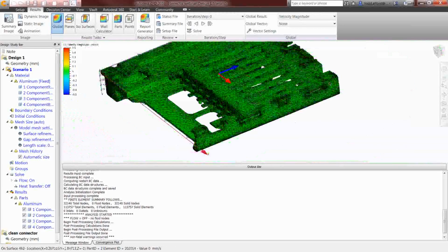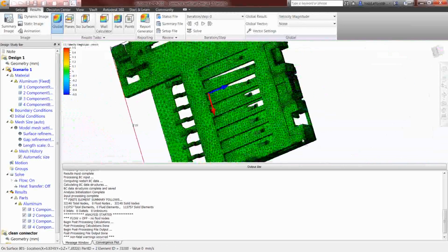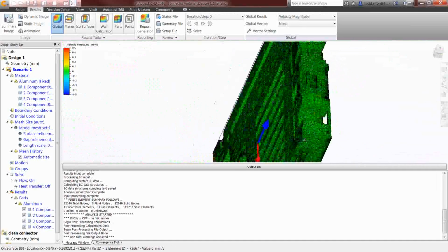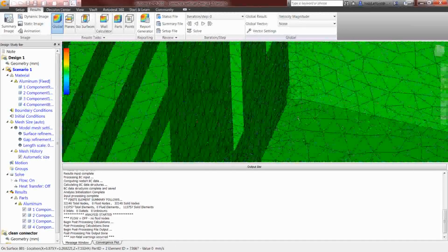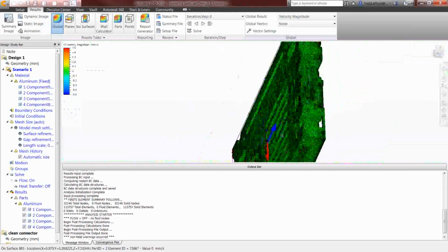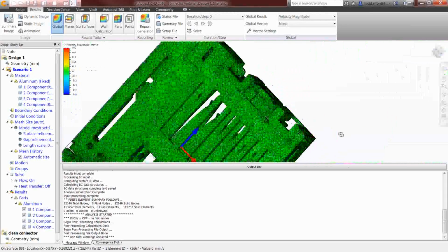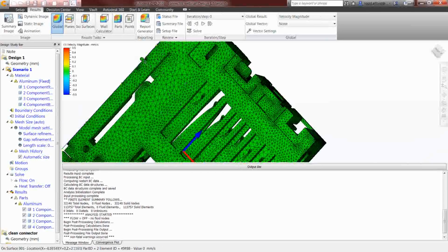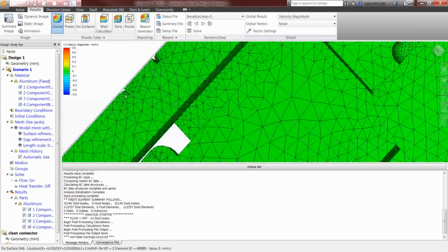And then I got rid of, where did we see those, these little slivers. When you look at the model zoomed out, we see that the mesh gets really tight by those corners, and then it grows out to areas where there's just not a lot of features. This being very thin, the mesh is still relatively fine, but you can see all of the areas where we start to get very small elements.